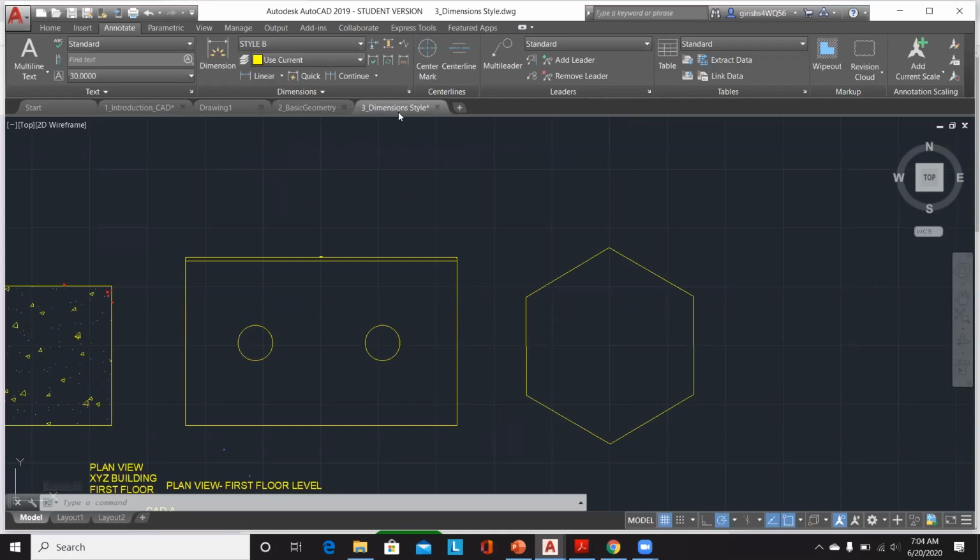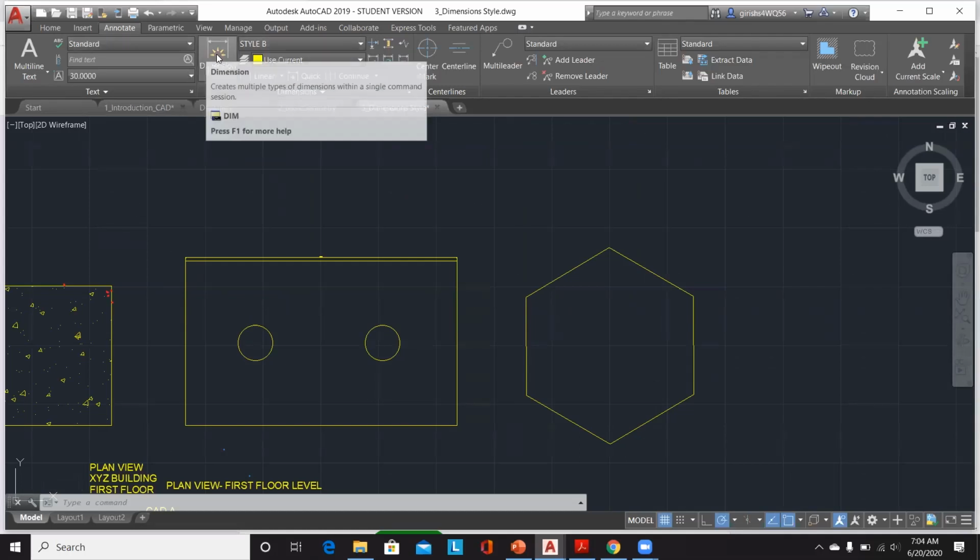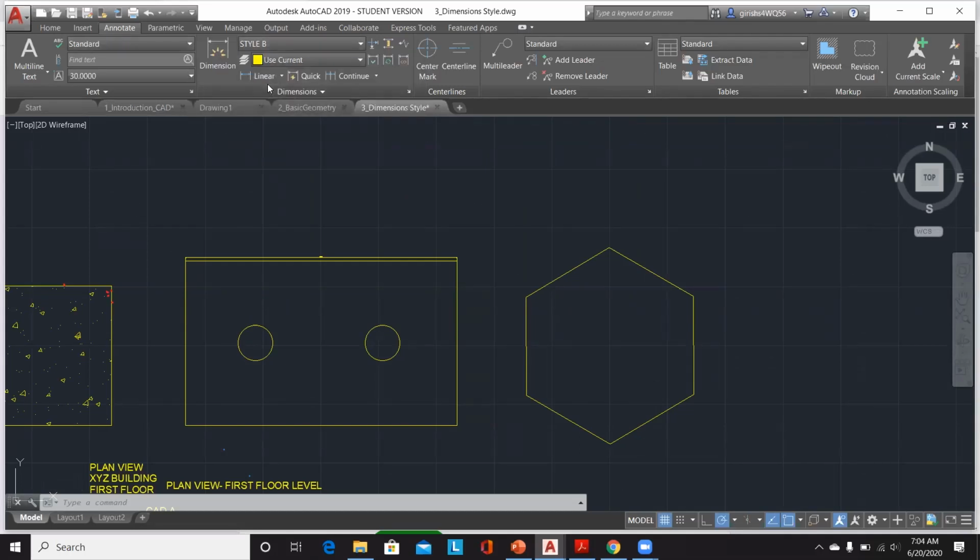What I can either do is, if I use the quick drawing phase, it will create all the dimensions, and some of those dimensions might not be necessary from the design point of view. So you can use the standard, let's say, create a dimension style, and use your dimension style to create these annotation settings. It will let you create reasonable dimensions based on your judgmental call.